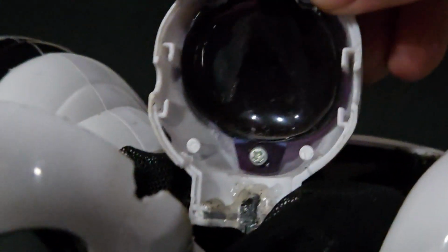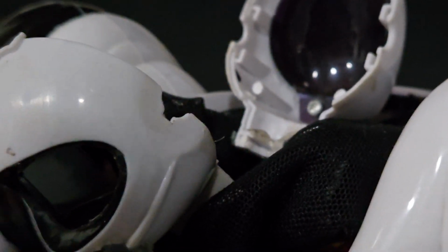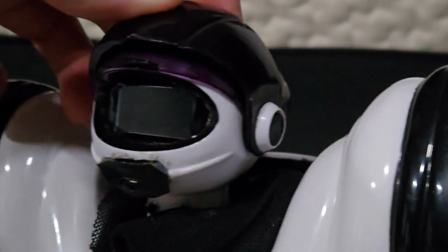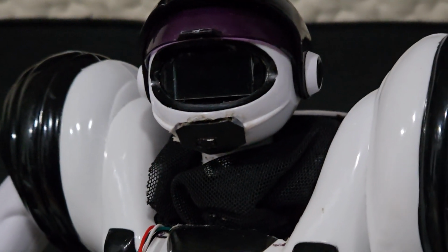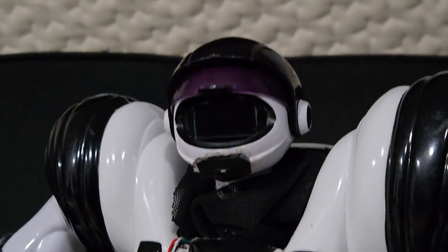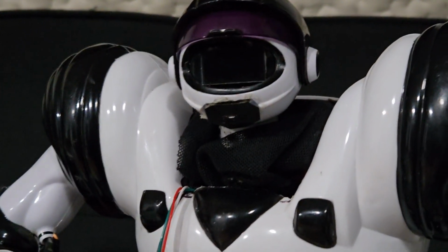And as for the way the head attaches to the servos, just make a river of adhesive and melt it into place so that it never comes free, and cut a notch in the back of the head. But don't go through the plastic, that'll compromise structural integrity. So that gives you a head that is fully actuatable and actually quite stable. Unfortunately though, a lot of Robosapiens won't take so kindly to you busting the head open. Only the newer ones seem to do really well with that, because the old plastics like to shatter and they adhered it together. So if you accidentally blow up your head, don't worry.